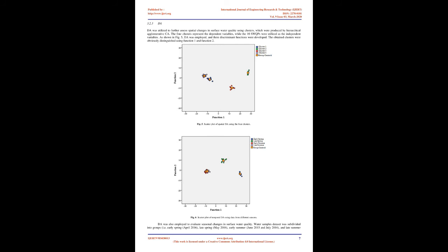PC2 verified that the loading value of EC was considered as strong with positive values, while pH was loaded as moderate. Hence, EC is the major SWQP responsible for spatio-temporal surface water quality changes in the SJR due to the existence of irrigation purposes. PC3 clarified that COD and BOD have strong positive loading values, due to industrial sewage, which may have resulted from food processing and paper production industries along the shoreline of the river. The above outcomes confirmed that PCA/FA is a cost-effective method in surface water quality research studies owing to its potential of classifying the most significant pollutants in the SJR.